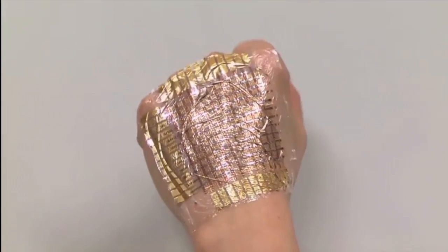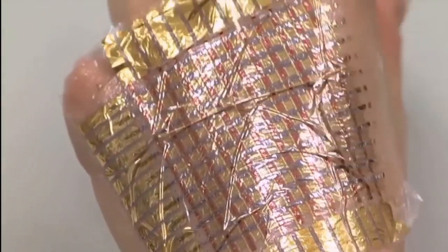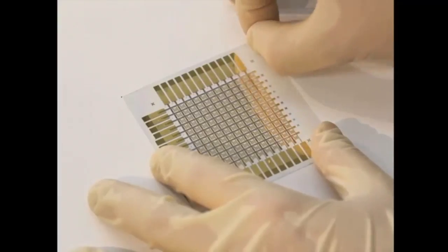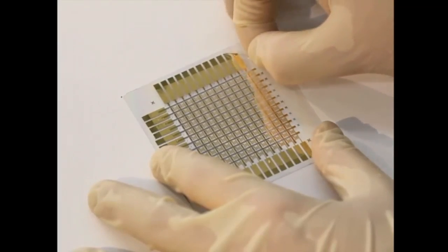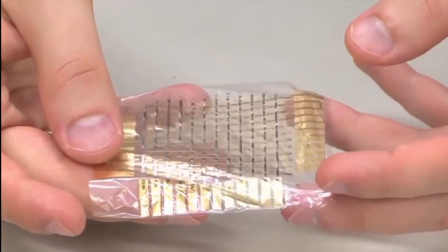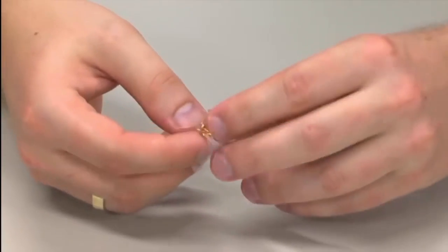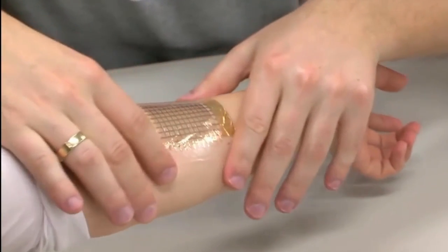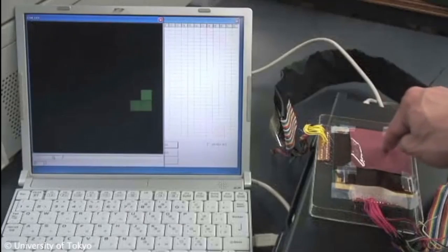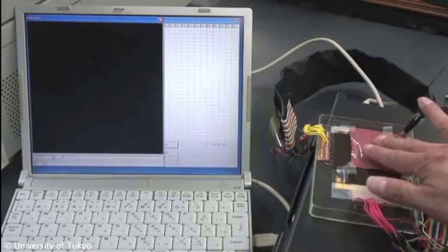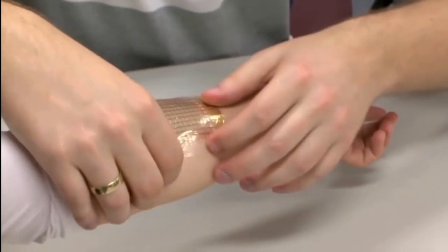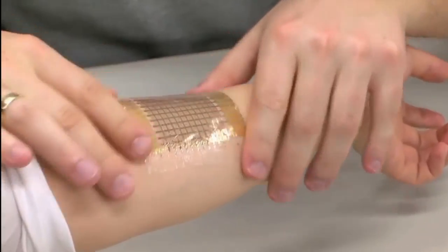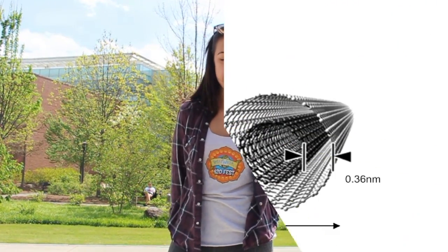Other applications of sensors can be used for electronic skins or implants to our organs. Highly sensitive flexible pressure sensors were developed by joining microstructured PDMS dielectric layers that were used in the fabrication of electronic skins that mimic the tactile sensing properties of natural skin. Both the sensitivity and pressure range are adjustable by changing the shape of the PDMS structures, and this system exhibited high pressure sensitivity. Now let's see some of our more advanced solutions for spinal injuries.